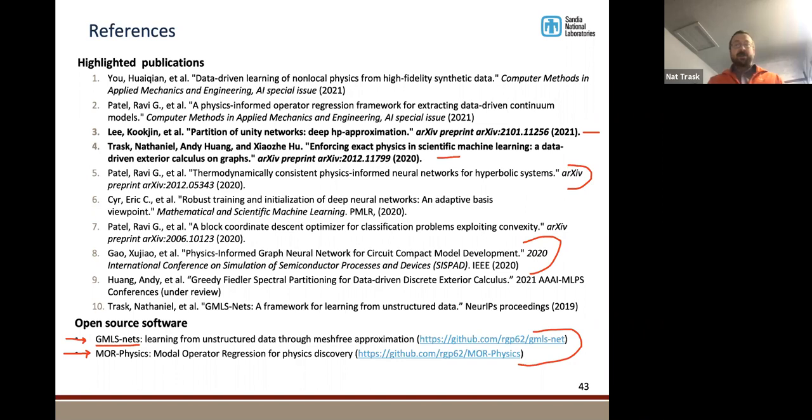Yeah, absolutely. So we're in a unique setting where there is no order of convergence, right? Because we're not trying to get a good answer through mesh refinement. We work on a very coarse grid, and then we get a good model by training it to fit a high fidelity set of data. So even though traditionally in the forward simulation world you would avoid a first order scheme, or maybe you wouldn't avoid it, but it would be the first step, in this setting it's actually perfectly effective, right?